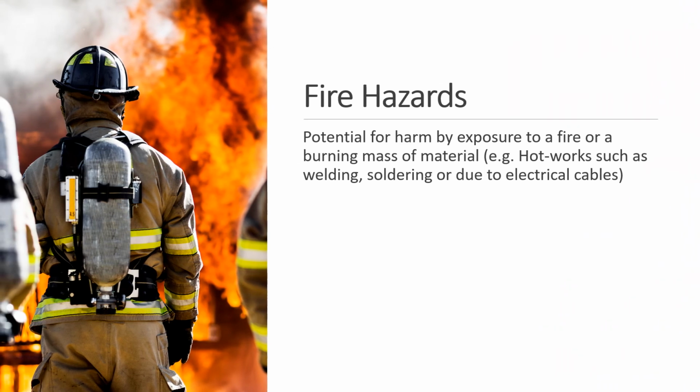Plumbers can also be exposed to fire hazards. You could have a potential for harm by exposing yourself to a fire or a burning mass of material, such as when performing hot works like welding or soldering, or due to poor electrical cables.